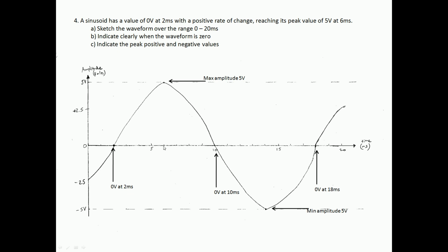And because it's a periodic repeatable wave, that means that it's going to be another 4 milliseconds before it's back down to the 0 crossing point again. So that's what I did. I drew this down, and in 4 milliseconds, we got to the next 0 crossing point, which was then at 10 milliseconds in time. And all we did was just then repeat it to go down.